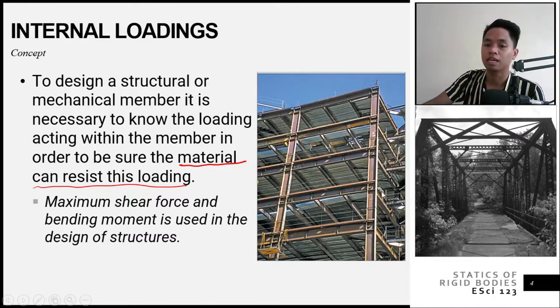So you cannot design, because you will encounter this in your principles of steel design. We have different steel sections: W sections, S sections, I sections, and many channels and angle bars. There are many sizes, like W8 by 14. Something like that, there are many different types of sections. Now, you cannot choose in your design, you cannot put any section, if you don't know the internal loadings occurring in that member.